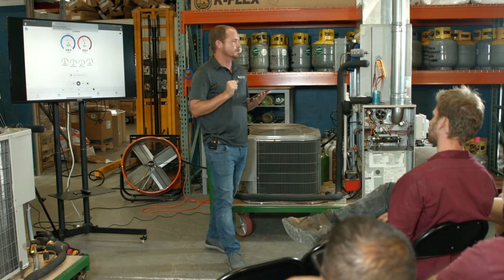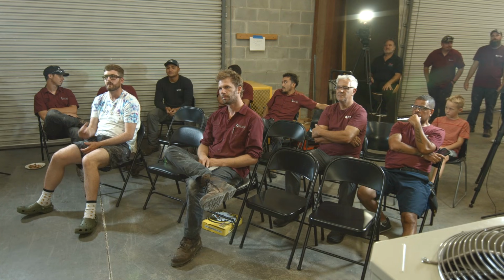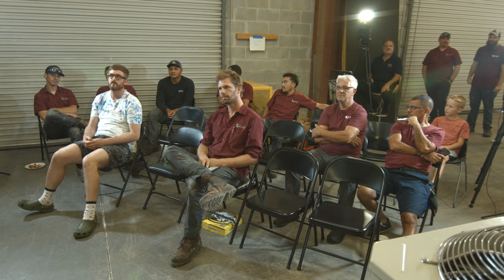And where do you see that in grocery refrigeration? When can that happen? Freezers. You see a lot of pressure limiting TXVs in freezers to not overload compressors. Yeah, but when do small systems typically overload?